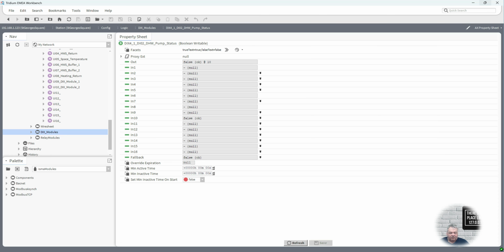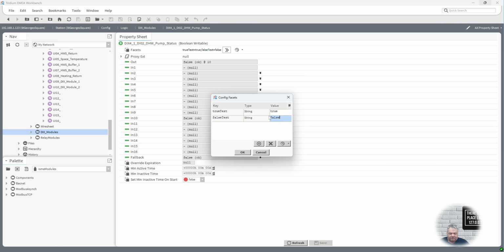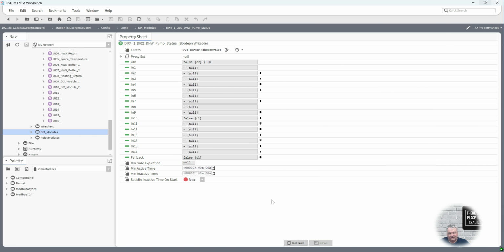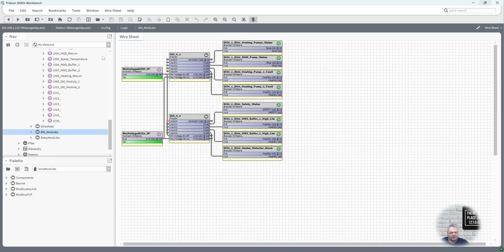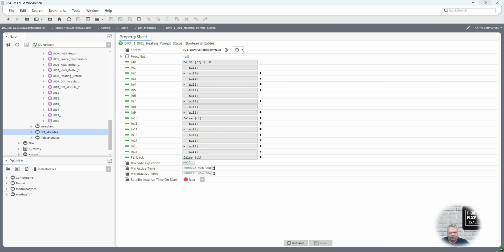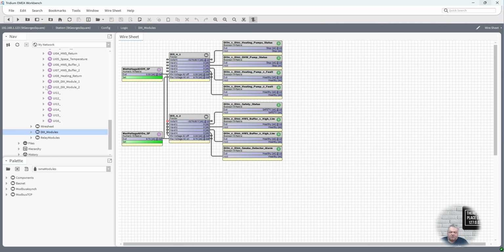Now this one is not going to have any alarms on at all. This is stop or run. It's not a DP, so it's not really a... I can't do flow and no flow because there's no differential pressure sensor. They're just CTs that are wound round, and it's just monitoring the current. Right, so that's them done.